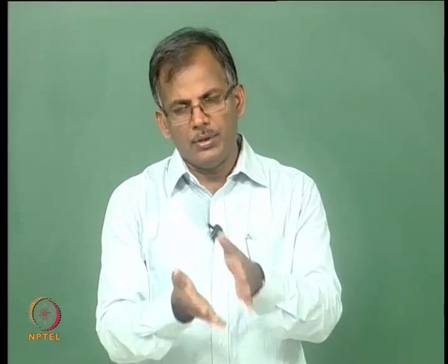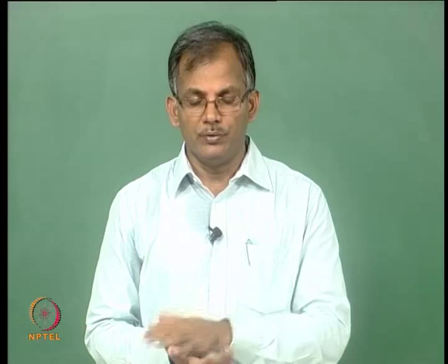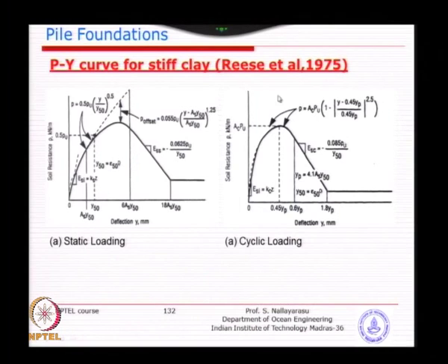The pile will come back creating a gap between the soil and the pile, and that is the biggest worry for mostly offshore piles, and that is what was investigated by Reese substantially.